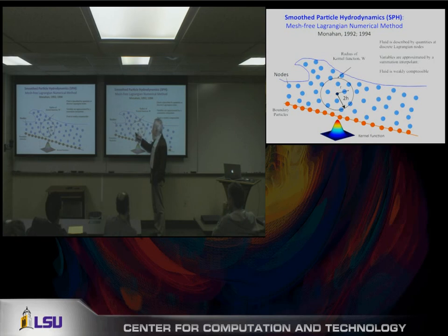One of the key things about smooth particle hydrodynamics is the idea of a kernel. When you're doing these kinds of particle methods, for a particle or a point at this location, if you want to know, say, the velocity or the pressure or something, you can just sample all the neighboring points in a weighted average, and that gives you the value at that point. It's like moving least squares. We do like a least squares fit here or here, and that gives you the value at different points. And in fact, half of SPH is just interpolation.